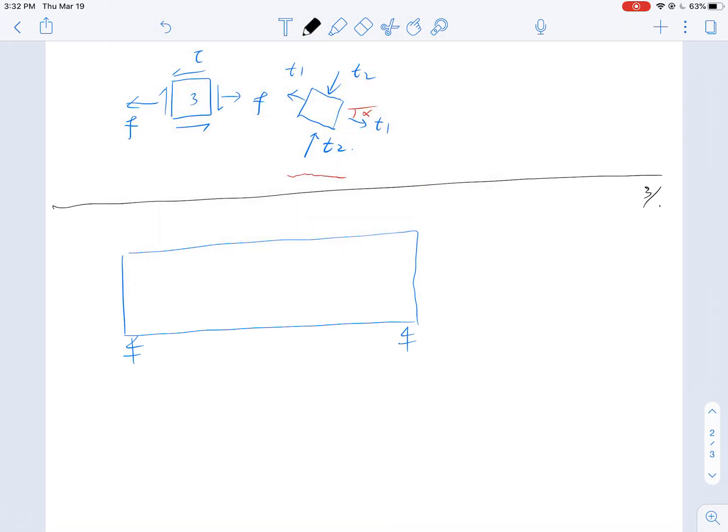Okay, I'm going to see the crack like this. I'm gonna have a crack like this, and my rebar is gonna be here. Okay, and then I can say that these cracks on the outside, I call these a bending crack or flexure crack.